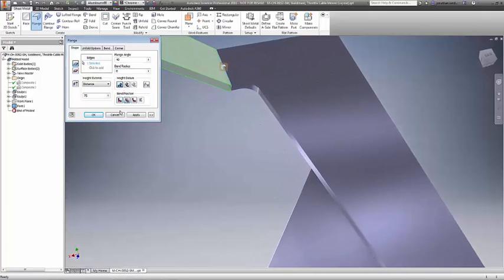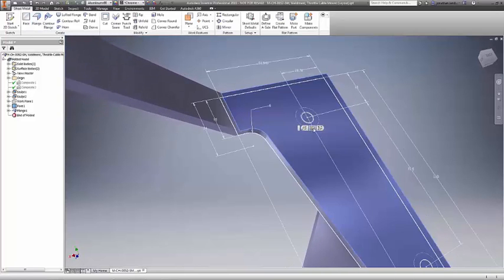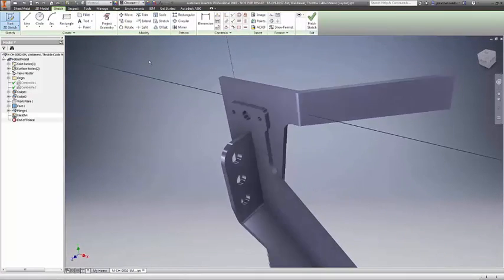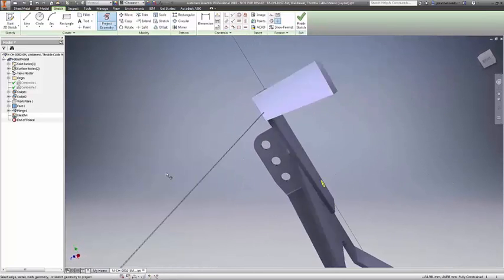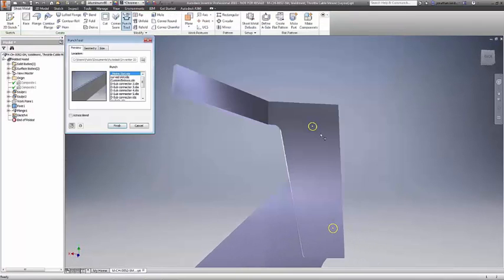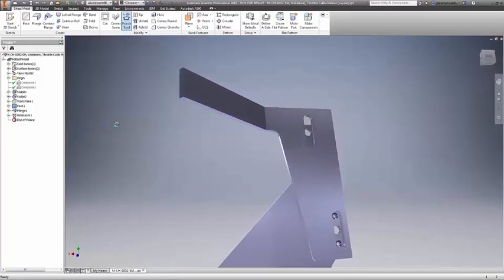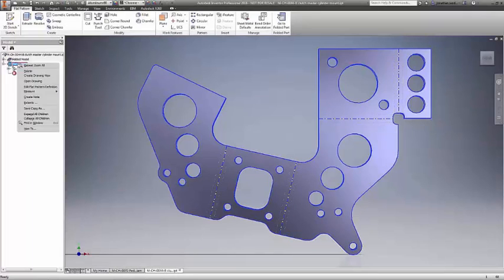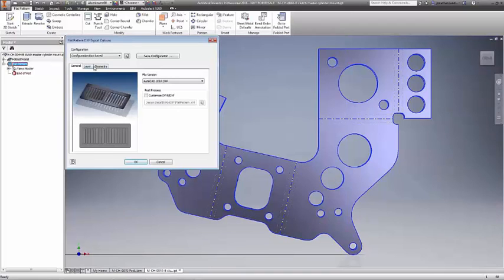There are also several other miscellaneous sheet metal enhancements that are now available inside 2016. First, you can create zero radius bends in any sheet metal component, enabling a more true-to-life fabrication method. Next, when placing multiple punches, get a quick count of the number of instances so you can include that information in the machine setup documentation. Finally, when exporting flat patterns as DXF, a new option allows you to trim center lines and contours, making the export of the DXF flat pattern more robust and usable than ever.